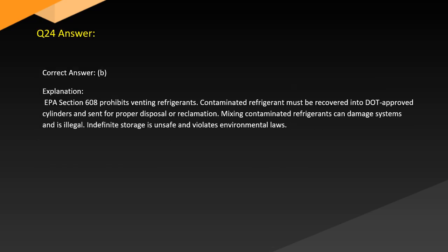Answer. Correct answer: B. Explanation. EPA Section 608 prohibits venting refrigerants. Contaminated refrigerant must be recovered into DOT-approved cylinders and sent for proper disposal or reclamation. Mixing contaminated refrigerants can damage systems and is illegal. Indefinite storage is unsafe and violates environmental laws.